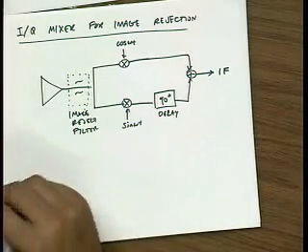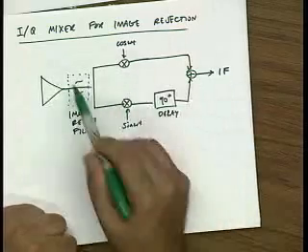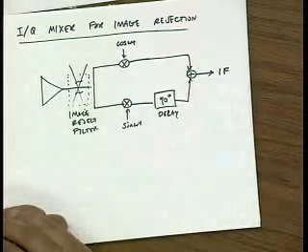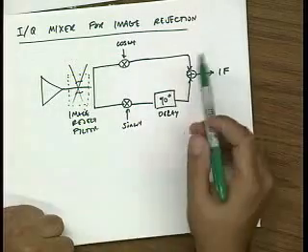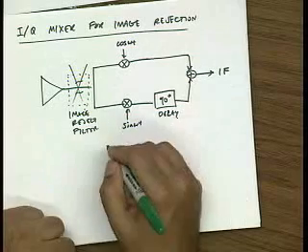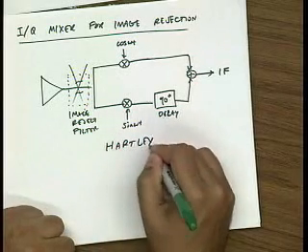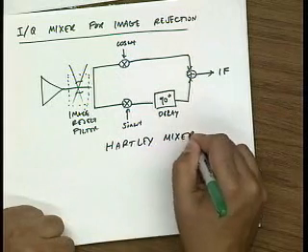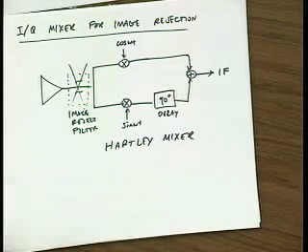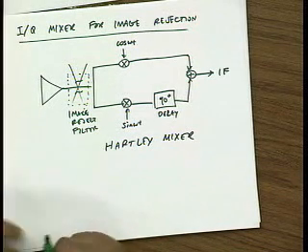And this lecture, what I'm claiming is that basically, if this thing were to work perfectly, you could get rid of this image reject filter. You wouldn't need it, because this is inherently an image reject mixer architecture. This one is called a Hartley mixer. Okay? So let's see how this works. And to do that, we're going to build it up point by point.